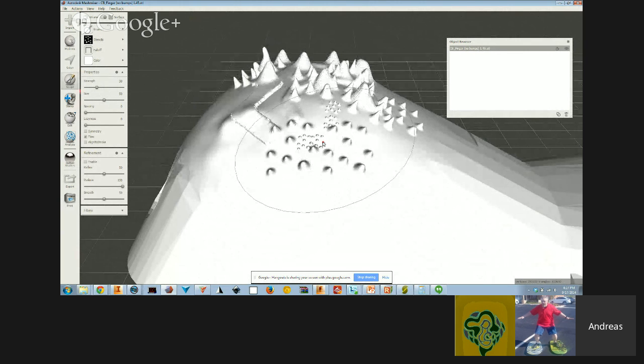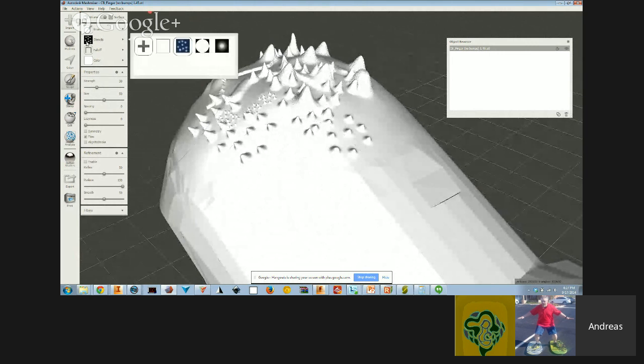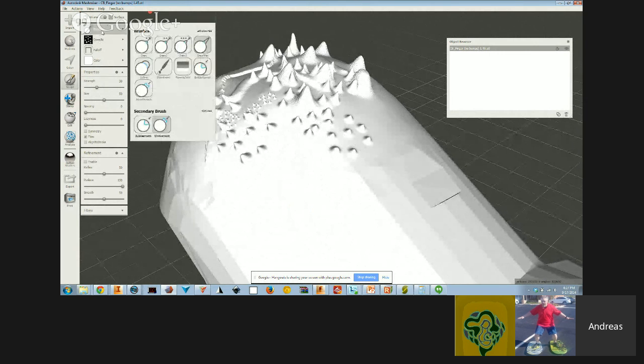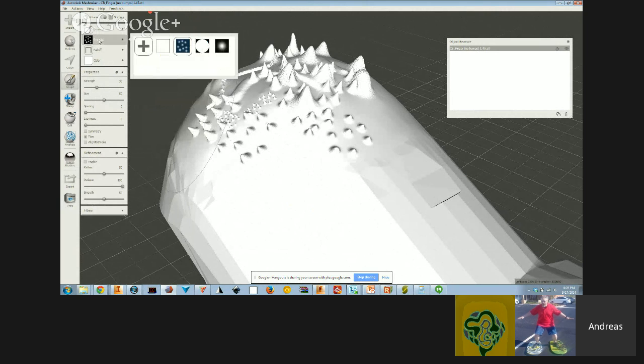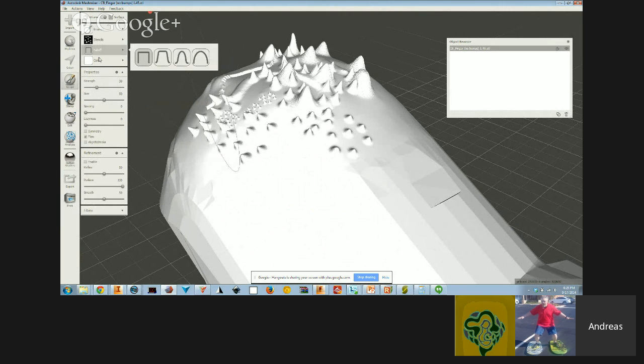Yep. Exactly. Well, that's basically using a stencil with one of the sculpt brushes. This is just scratching the surface of some of these things. Again, I toggle this over to surface, and I use this draw max, and then I added a stencil. You can import one from your hard drive using this. Change your falloff to full or not, and then make your brush size the size you need, and you can start to adjust that geometry. Again, you need to make sure you have the geometry there.